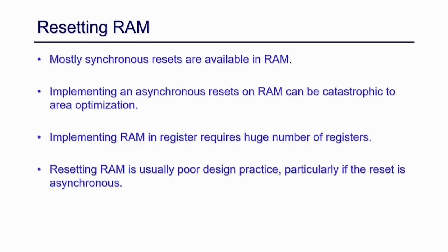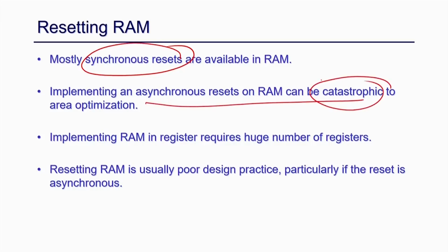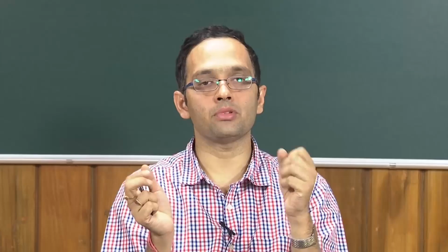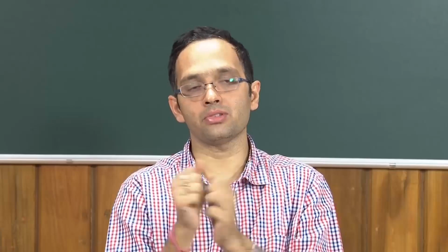Okay. So, now we are going to talk about the RAM. We have discussed shift registers and DSPs, now we are going to discuss the pin configuration of RAM. RAM has synchronous reset, it does not have any asynchronous reset or asynchronous set. If you use any asynchronous reset in your design, it has a catastrophic impact on your optimization, because the RAM is a big unit and you cannot map the whole thing. If you do not map that into RAM, it will be mapped to registers, and this is a disaster, because that will consume a lot of registers in your design.